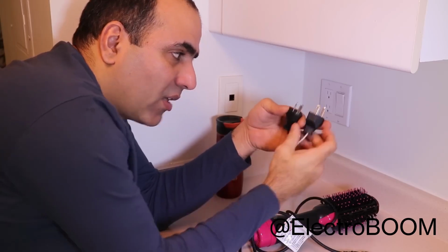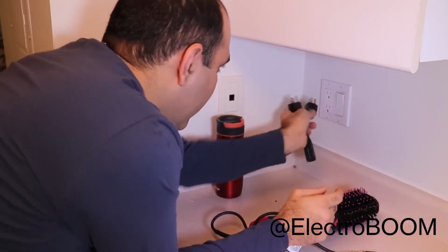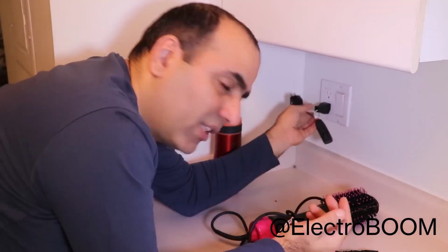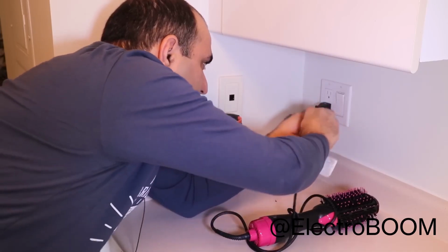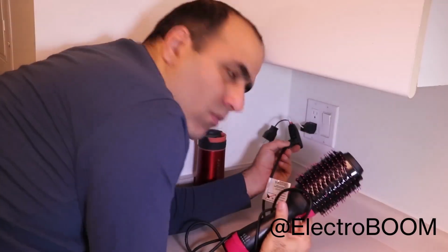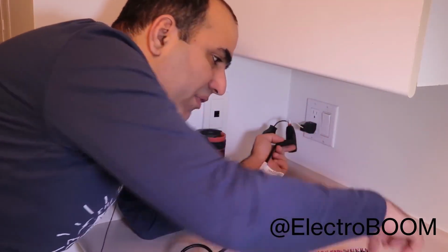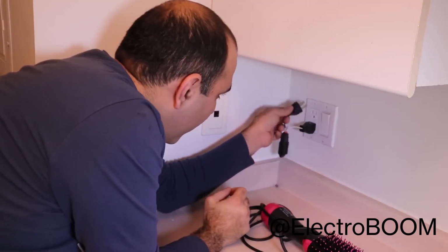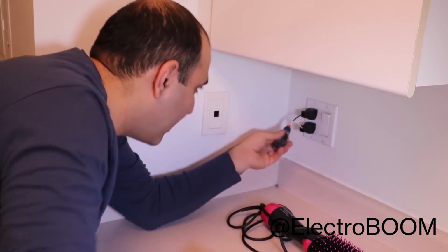Here we are. Every wire of the outlet is connected to the live of one of these plugs. And even if we just plug in one of them, it is still safe to touch the other one because it's not connected anywhere. Now if we connect the hairdryer... I was wrong. If you plug in a hairdryer that's on, the live voltage will travel through the hairdryer to the other plug. So this is live now. It's only safe if you plug both of them in first and then plug in the hairdryer. If you plug the one end in and turn on the breaker, the other end becomes energized at 120 volts through the relay coil, as you can see here.